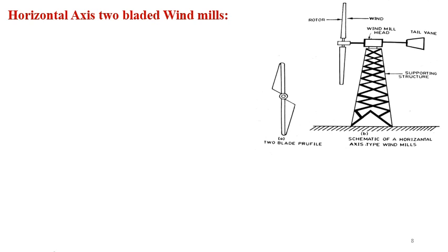So this may cause serious damage. If the vibrational modes of the rotor happen to coincide with one of the natural modes of vibration of the tower, the system may shake. Because of the high cost of blade rotors, more than two blades are not recommended.